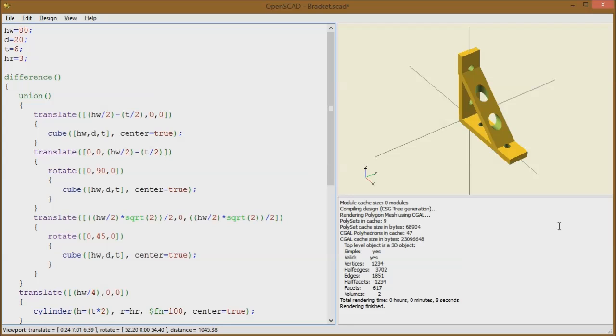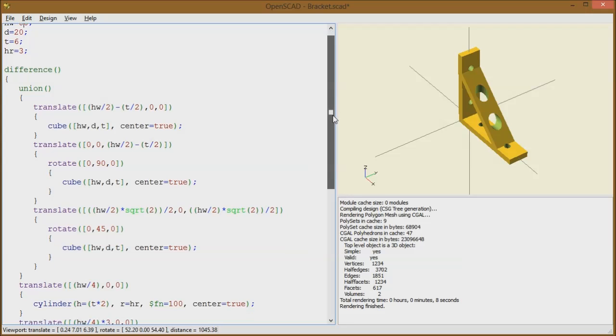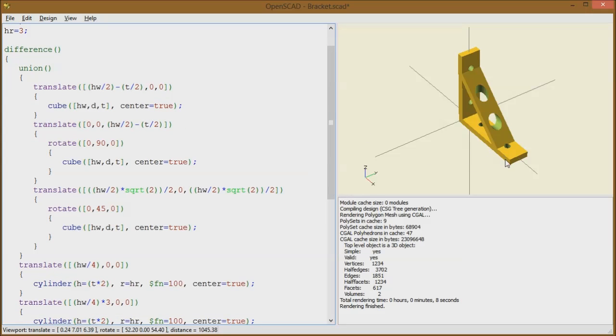To add rounded corners in OpenSCAD, the easiest way to do this, so you could go ahead and generate a cylinder there and a cylinder there, put a square in, or put a square on the outside actually, and then use that as a cutout model on top of this. Another option is to simply use a library.